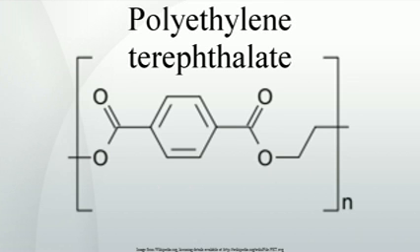Antimony. Antimony, Sb, is a metalloid element that is used as a catalyst in the form of compounds such as antimony trioxide, Sb2O3, or antimony triacetate in the production of PET. After manufacturing, a detectable amount of antimony can be found on the surface of the product. This residue can be removed with washing. Antimony also remains in the material itself and can, thus, migrate out into food and drinks.